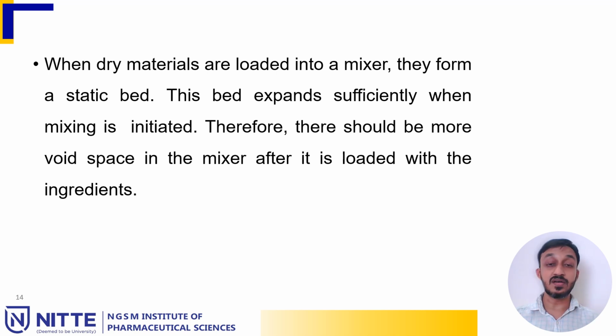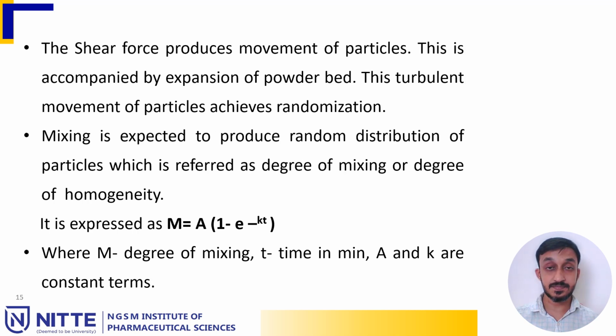When dry materials are loaded into a mixer, they form a static bed. This bed expands sufficiently when mixing is initiated. Therefore, there should be more void space in the mixer after it is loaded with the ingredients. In order to compensate for the expansion of the material, there should be sufficient free space. The shear force produces movement of particles. This is accompanied by expansion of the powder bed. This turbulent movement of the particles achieves randomization.